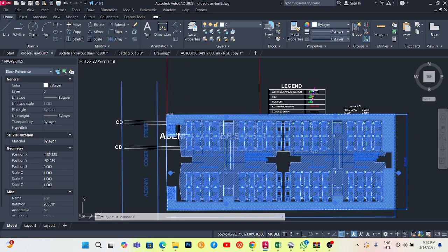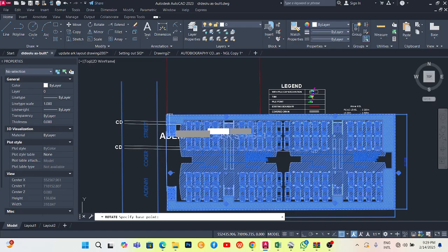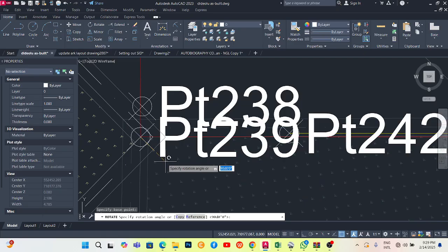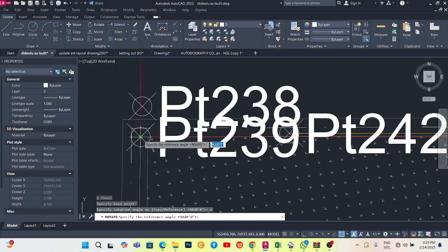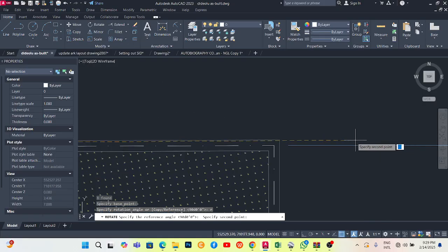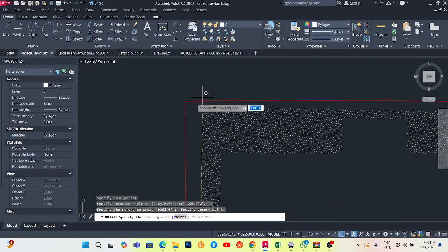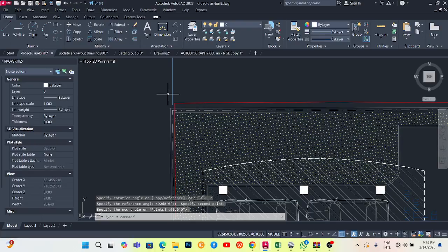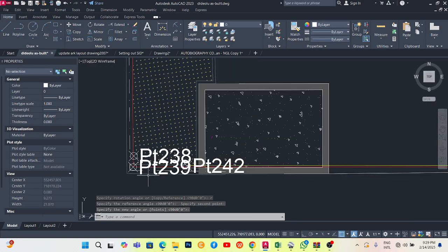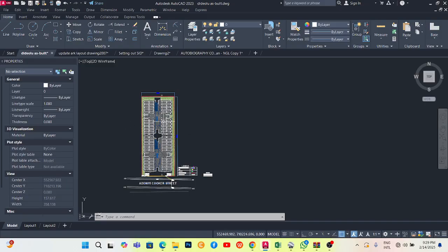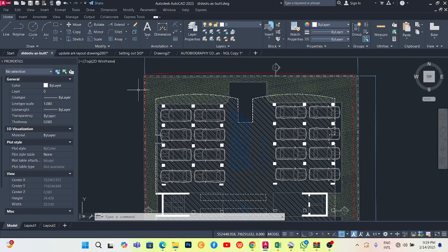Once I click the one I want to orient, I'll type R, enter. That is to rotate with angle. I'll click the point again, then click the end point here. Then I'll drag it to this upper part. So you can see, guys, that there is a little difference, because the aspect that I did, I picked the wall fence from inside the site in the perimeter. That's why I'm using that point.